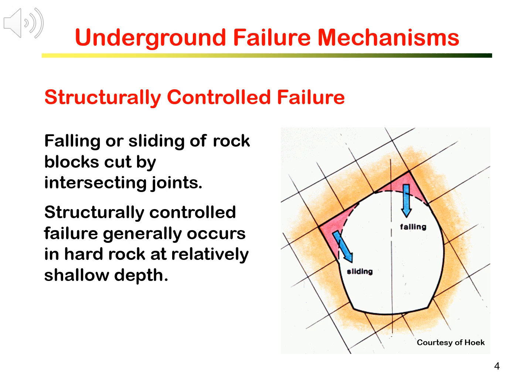This type of failure is termed structurally controlled failure, as the blocks and the wedges are controlled by the discontinuity structures, and sliding is along those discontinuity structures.